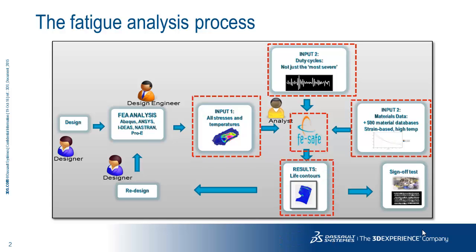So as you can see in this process, whatever finite element analysis you use, if you are using ANSYS for this particular process, first of all you have to solve your ANSYS model, then you have to use whatever output you are taking from the ANSYS model into FE-SAFE. You need to open your FE-SAFE GUI, and then it will write the model in an RST file, which you can again open using ANSYS Mechanical. So there is a lot of manual labor which is involved in this workflow.